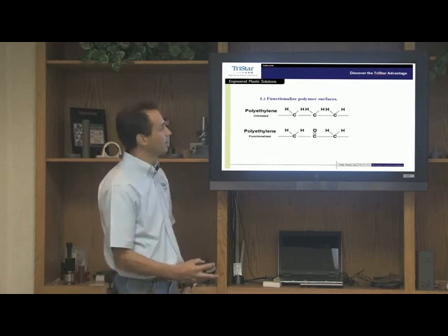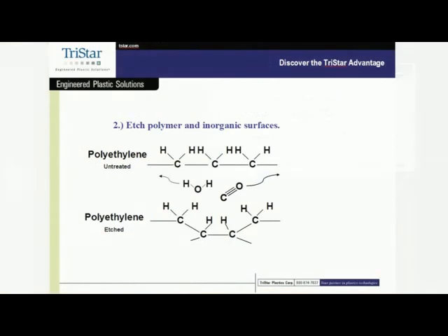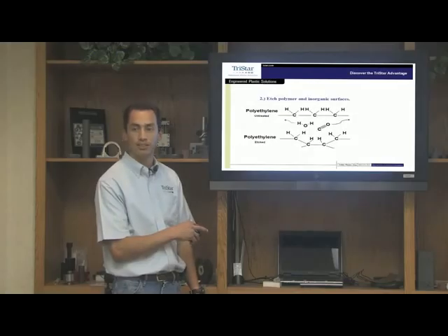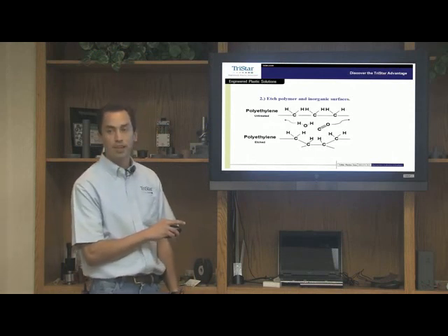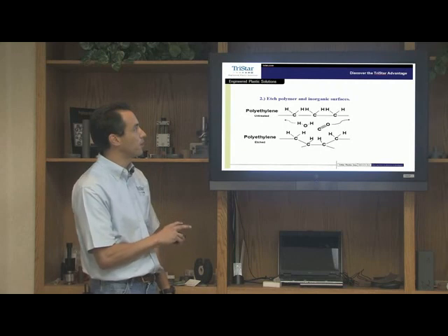If I take that process further, I'll begin to etch the material. And if you remember, that's one of our adhesion mechanisms. Not only are we creating bonding sites through covalent bonding and hydrogen bonding, but we can do it also with mechanical roughness. So if we just continue processing the part, we create little pits and valleys, enhancing our adhesion. So etching a polymer and activating a polymer is all a part of plasma processing.